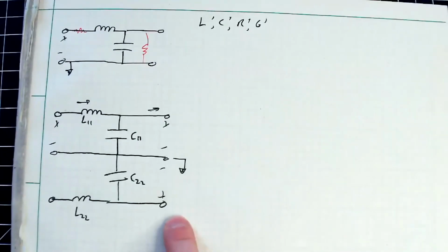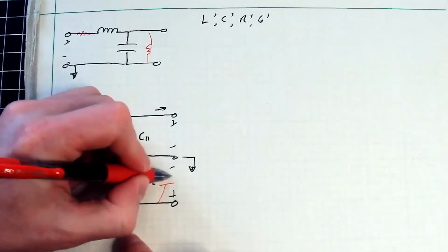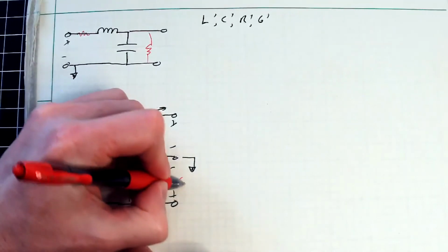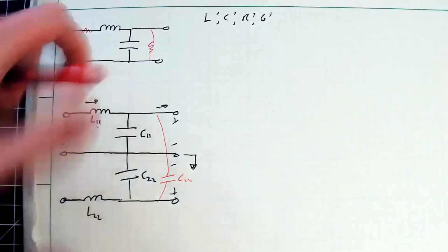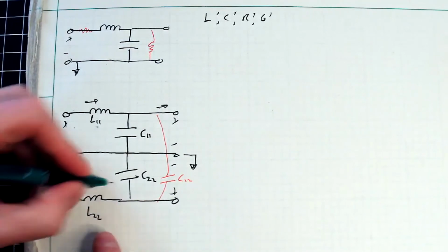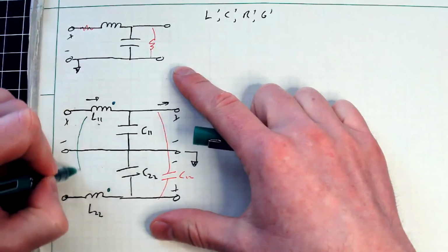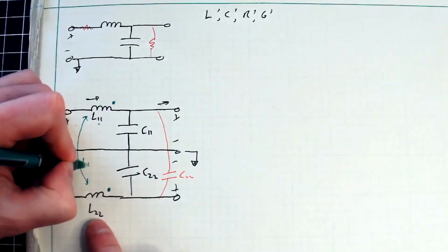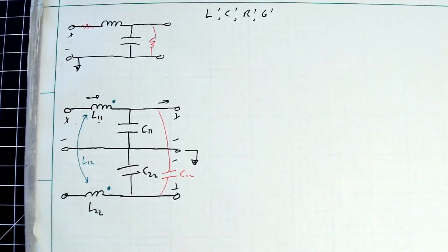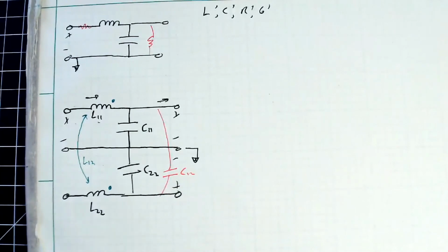Only when I have multiple conductors around, I might also have some crosstalk between them, which we call C12. There's also some mutual inductance between these, so I would use the transformer notation and call that L12. I can do this arbitrarily: I could add 20 different lines, and each one would have one of these crosstalk terms to the others.